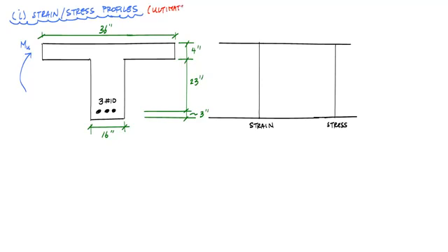But the thing to remember here is that you are drawing this strain and stress profile at ultimate. And this word ultimate implies a specific strain value for the compressive strain. In this case, the concrete is crushing. And so here, that means the compressive strain in concrete reaches the ultimate compressive strain. And if you're using the American Concrete Institute standard, this is 0.003 in compression. And here I will have a linear strain profile, and that linear strain profile is always true.